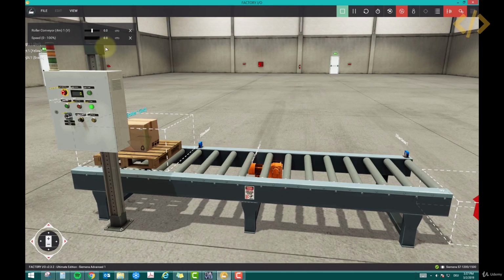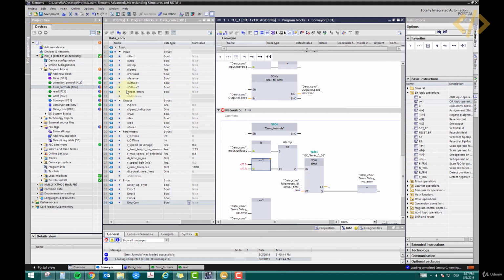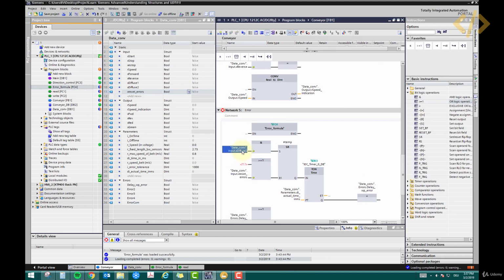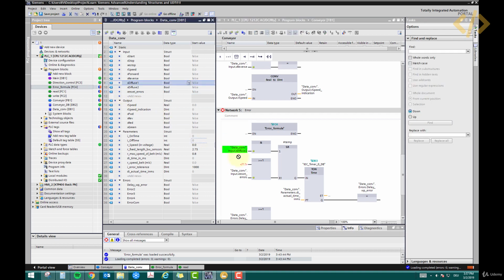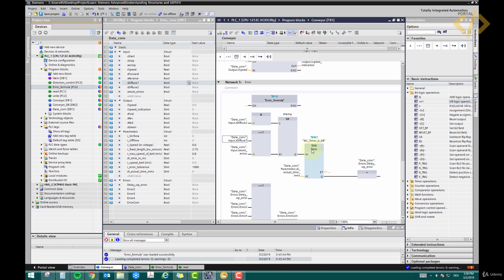And the reset button, I0.7. I think we already took it here. Yes, reset errors. So it will be reset by the reset error and another sensor, because we have to reset the timer. In an ideal situation, this timer should be reset, because if the timer is not reset, it will actuate the error, which we ideally don't want. But if there is an error, to reset the timer, we use the reset switch here. So I hope everything is good.